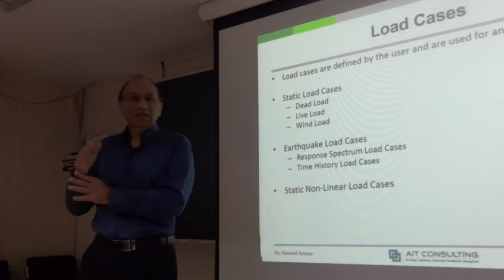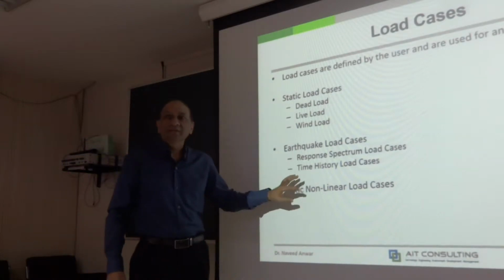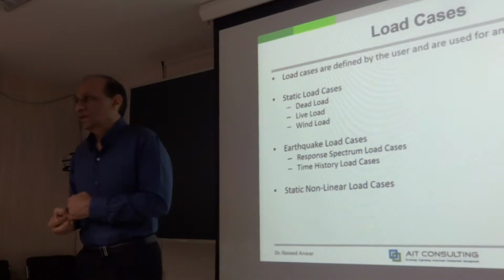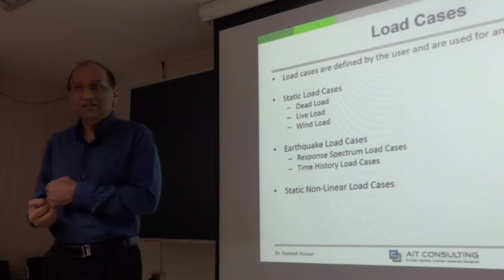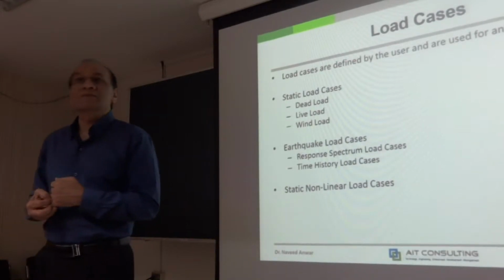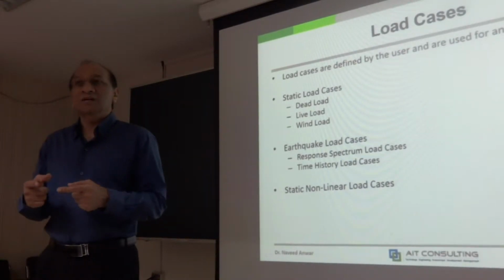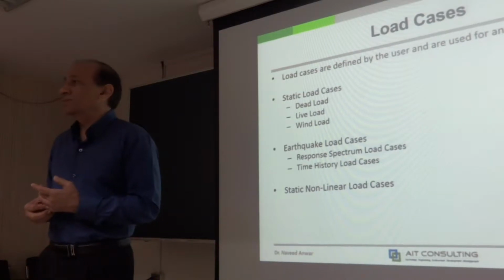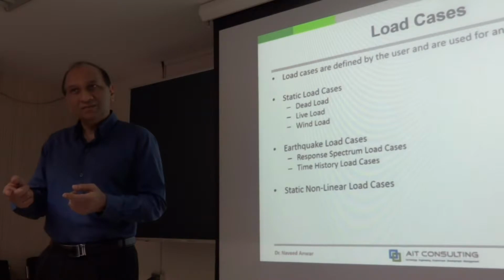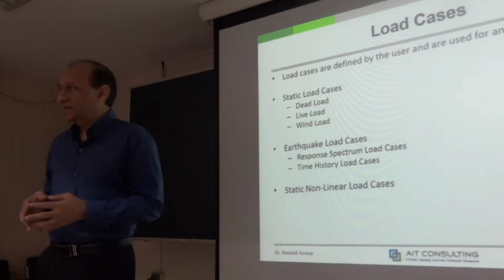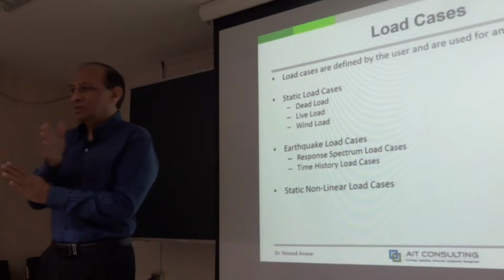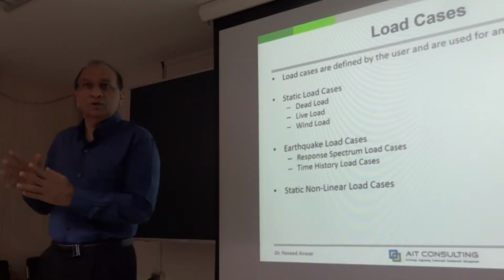And then during that time there will be non-linearity, cracking, so the structure will change. So not only the loads will change, but the structure that you modeled will also change. In the beginning there was no cracking. Now some columns start to crack, properties have changed, moment of inertia have changed. So we have to update the properties, we have also to update the cases, then continue, and if we find that this is too far, go back, try again, and so on and so forth.